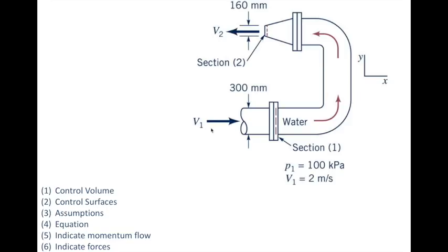But we do have a momentum entering our system on the lower part of the pipe. We have momentum exiting our system up above. We do have a force due to pressure here. And this one is also making you think a little bit about your pressures because within the problem, you're first given a gauge pressure for pressure at cross-section 1, and then an atmospheric pressure for that at section 2. And that's a little bit of a trick question, so I'm reminding you of that.